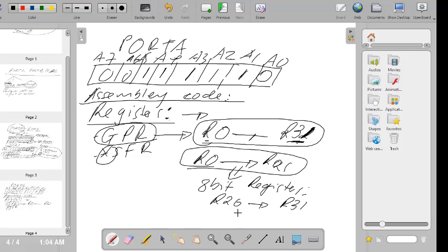We'll talk about these in general later, but right now I just want you to understand that the XYZ registers, 26, 27, 28, 29, and 30, 31, are 16-bit long, meaning they can pack 16 bits of information, while the others pack 8 bits, which is what you see here: 1, 2, 3, 4, 5, 6, 7, 8, and these can pack 16.